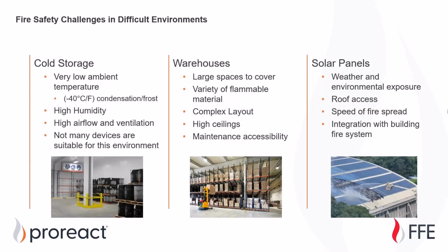So there's going to be different challenges with every project. Environmental challenges for a cold storage warehouse. Obviously, you have the low temperatures. Not a lot of devices are rated or even suitable to go down into the negatives, negative C, negative F. So you have, just to begin with, very low ambient temperatures. Some of these cold freezers can go down to negative 60 C, negative 40 C is pretty common. The ProReact, our linear heat detection cable, is rated down to negative 40 C, which also happens to be negative 40 F. And we have high confidence that it is suitable, even lower than that.